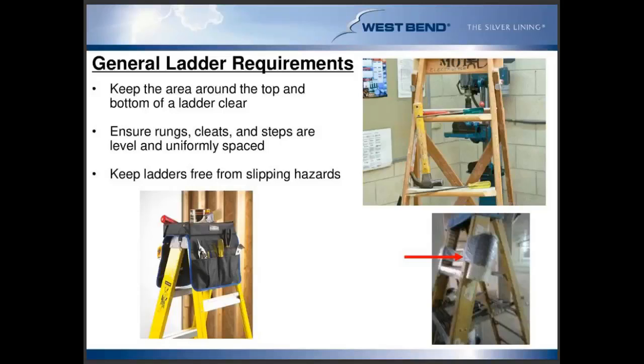The picture to the right is just another option that I've seen out in the construction field, where an old PVC section of pipe was duct taped to the side rail. Again, while it might not be ideal, given that the duct tape could be covering up some defects that the ladder may have, like cracks on the side rails, it's still something that is going to hold and contain tools and keep them readily available.